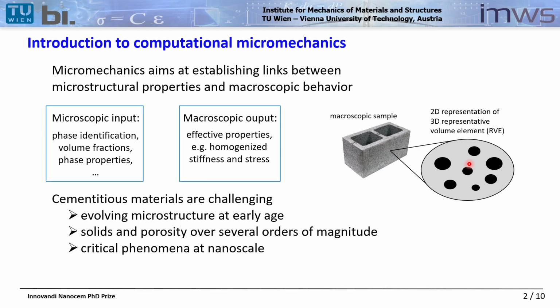Cementitious materials are particularly challenging to use in multiscale mechanics because they present an evolving microstructure at early ages, and the solid constituents and the porosity range over several orders of magnitude, from gel pores of a few nanometers to aggregates in concrete of a few centimeters.